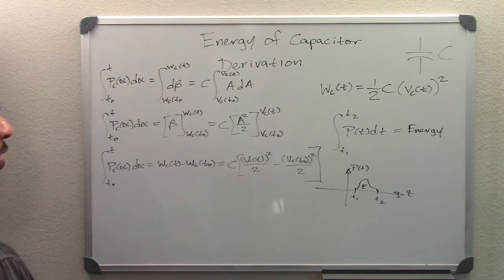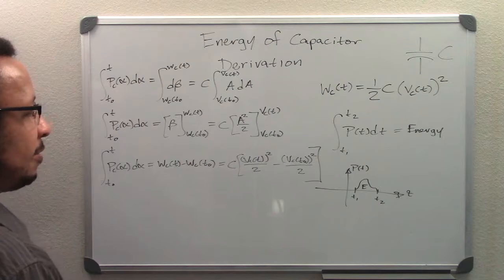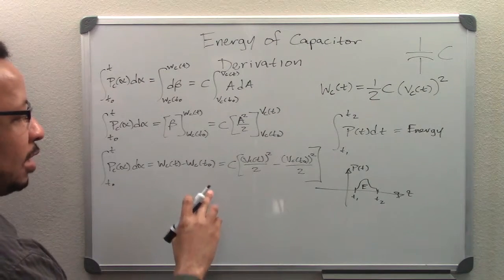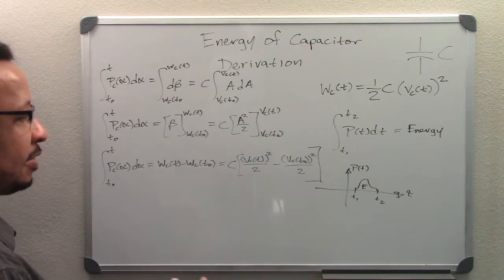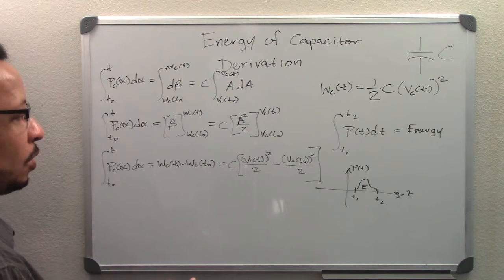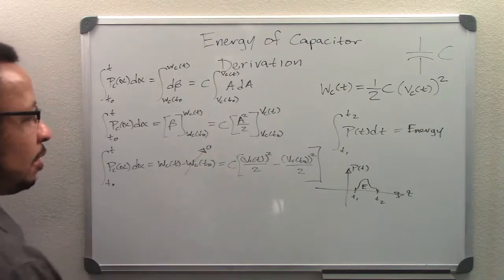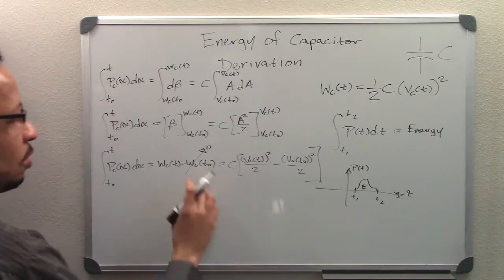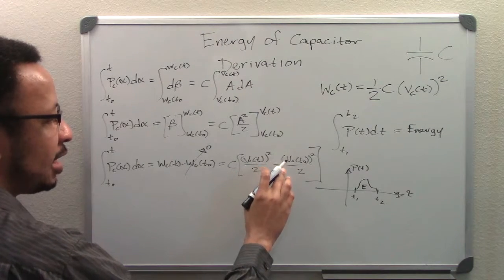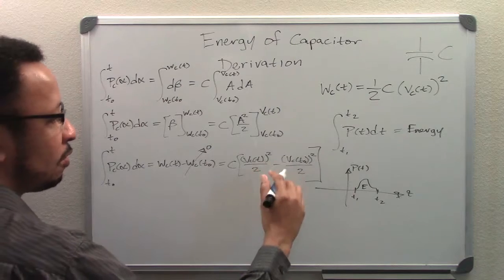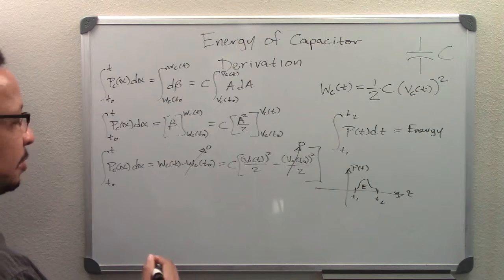And so next what we'll take notice of is that we can reduce this a bit due to the fact that usually the energy of the capacitor at time equals 0 is 0 at that given point. Usually they bring that out and say that it's 0, so it simplifies things, and that corresponds to our C times negative Vc of t sub 0 squared over 2 over here. So this term is zeroed out as well because you have a direct correspondence.